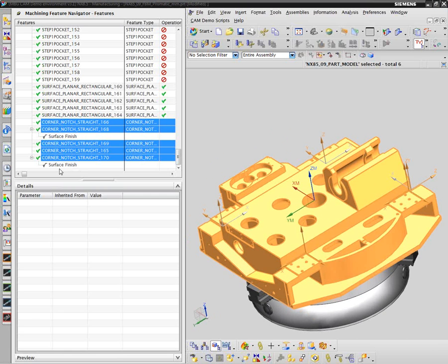In this case, we've got 2 surface finish callouts on these particular surfaces. Okay. NX will not only recognize feature types, but it also finds this PMI information, and then by using the machining knowledge editor to create rules for operations, it will help determine what type of operation to apply to these and what type of tools to pick for these different types of PMI information.